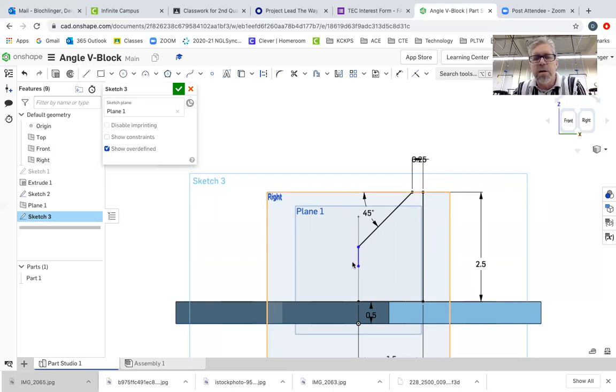Delete. And I'm going to delete this one. And yeah, I need to go L for line. The book tells me from here, we're coming up 0.75. Okay, then we're coming out half of 0.25, right? And then it goes up for our intersection. This needs to be a parallel line, vertical. All right, so that should get me where I'm going.